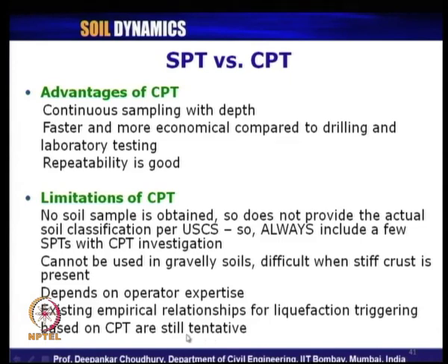This is most important in our study. That is, the relationship between CRR and SPT, the points, the field observations whatever have been collected and reported by several researchers, those are quite well established till date. Whereas, for the case of CPT, it is not so well established like SPT in terms of liquefaction triggering analysis. So, it needs further study.